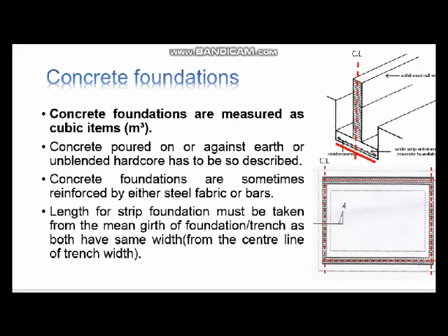Okay, then after you find the length, the perimeter, you just multiply with the width and the height of your concrete foundation. Then you will get the cubic meter of your foundation.